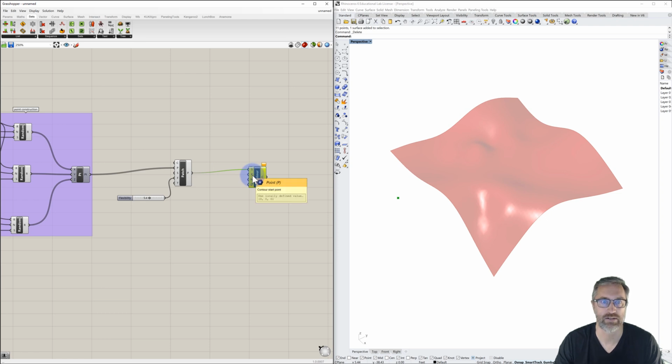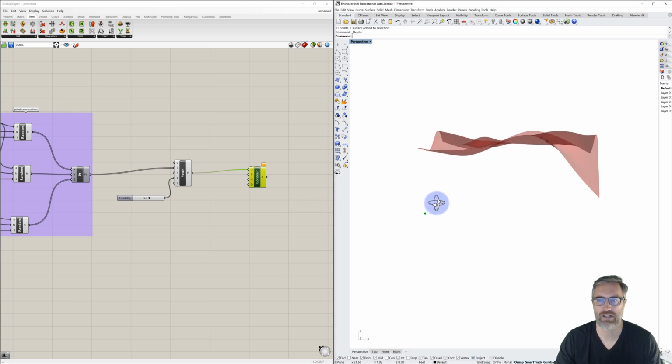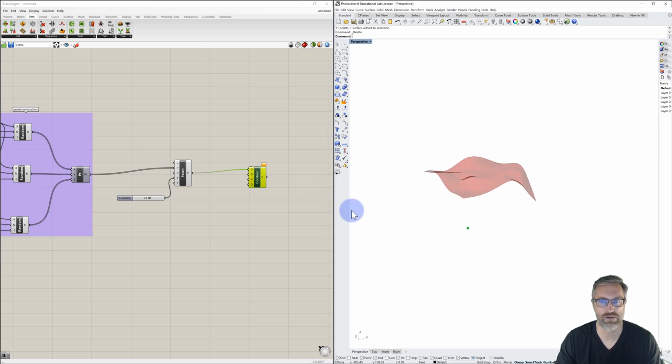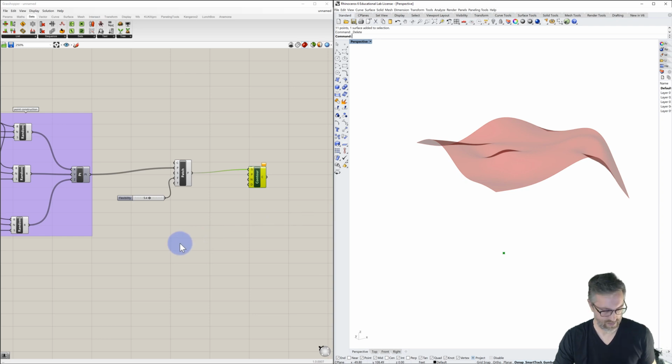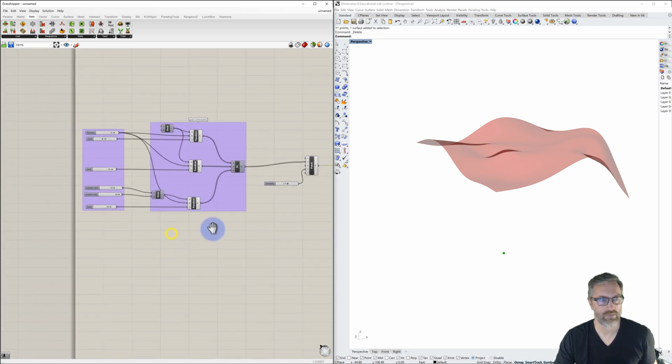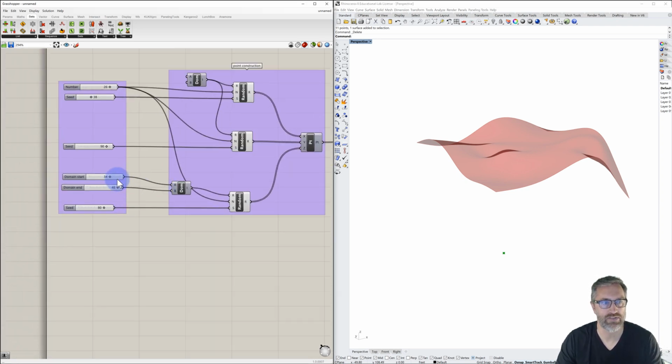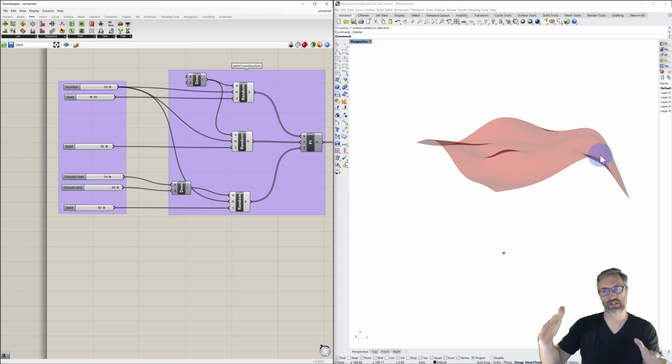It needs a contour start point. This is defined as 0, 0, 0. And depending on what you did with your domain for your z value, you may want to increase these, because if you have part of your surface that's coming down like it is in mine, and if that's below that point, it won't contour it.